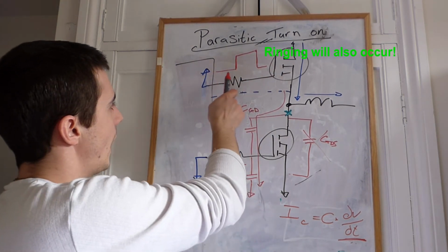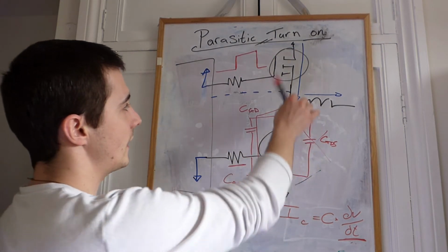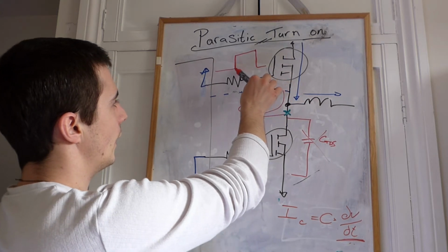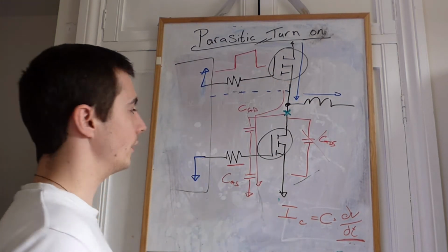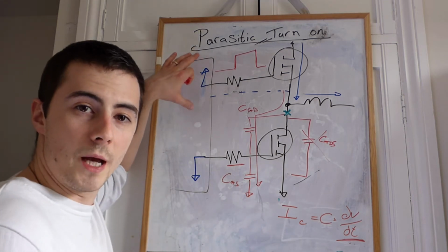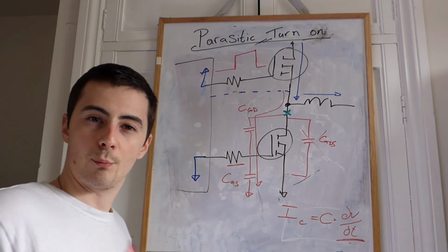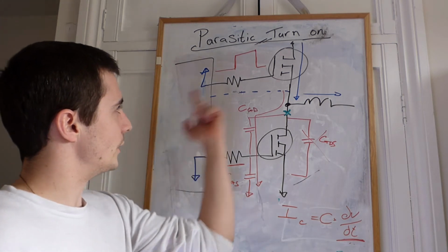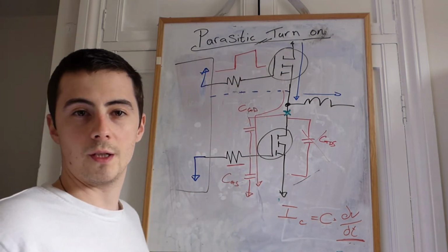because we've got these parasitic capacitances and the gate is essentially a capacitor. If you do a very sharp change, you're going to be pulsing a lot of current from your driver chip. It may not be able to source that current. These can usually source up to sort of 1 to 2 amps pulse current. But you could be pulling a lot more than that by doing this very fast. And it's also pretty bad for EMC reasons as well.